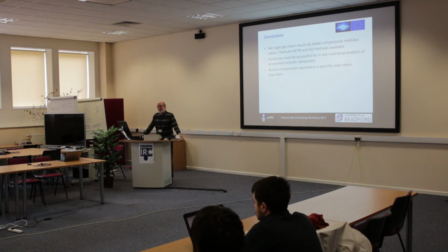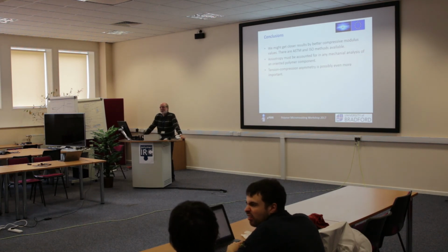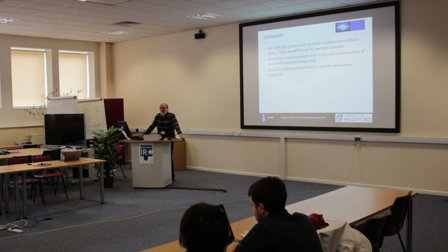Well, I'm sure it can cause problems. It can cause problems in processing, when you have crystallinity happening when you don't want it. If you're trying to draw something and it starts to crystallise while drawing it, that's going to be a problem. But with polymers, when you've got an actual component, you're not going to strain it enough, we hope, to induce crystallisation.